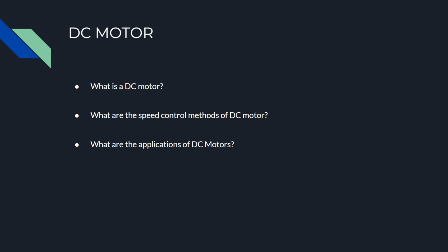Shunt motors. The shunt motors are used where constant speed is required and starting conditions are not severe. The various applications of DC shunt motor are in lathe machines, centrifugal pumps, fans, blowers, conveyors, lifts, spinning machines, etc. Compound motors. The compound motors are used where higher starting torque and fairly constant speed is required. The examples of usage of compound motors are in pressers, conveyors, elevators, rolling mills, heavy planners, etc.